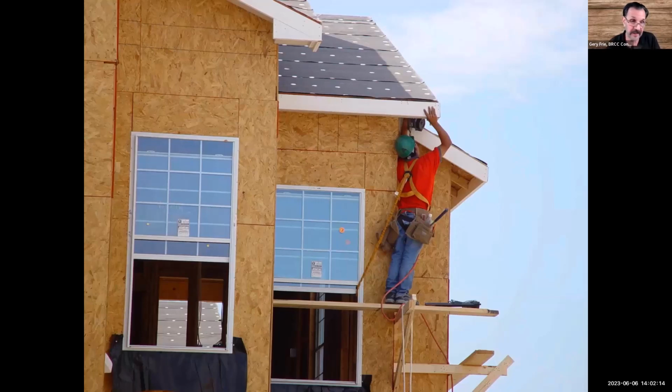Also, that's not likely safety glass. So when he falls, he's going to yank that glass out, and he'll have shards of glass raining down upon him. So that won't be good either. But as far as fall protection is concerned, he's going to fall a lot more than 2 feet before the system starts slowing him down, and he'll slam against the building too. So that's not particularly good.